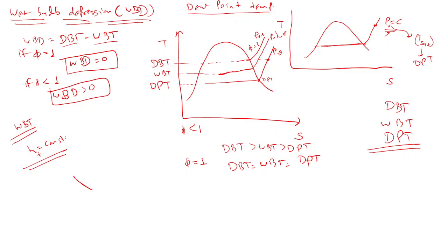We usually know the initial condition of air and the final condition, like temperature or relative humidity, two things we would be knowing, and then we can fix our point. Till that final point we go along the constant enthalpy line. By moving along constant enthalpy, we get the condition.